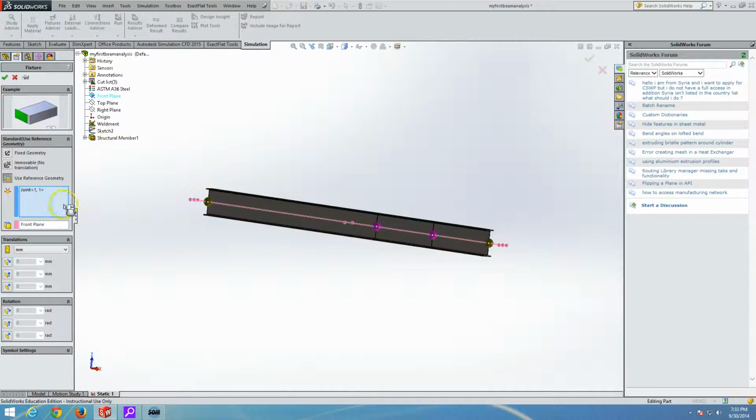And now I'm going to constrain it. It cannot move in and out of plane, and it can't rotate in any direction. It can't rotate in Y and in Z direction. It can't rotate along the plane direction. Okay, click OK.